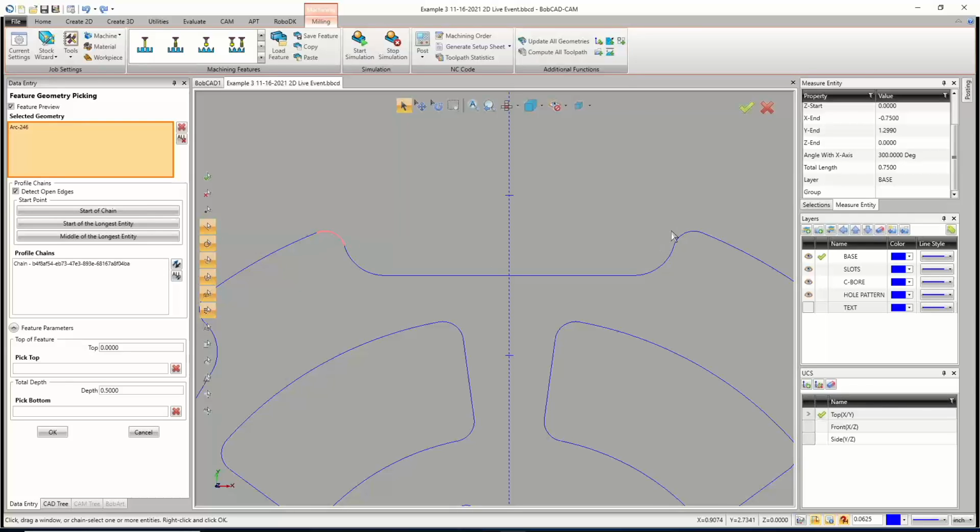You don't actually have to follow the chain. You could just jump over to it. But we want to go to the final radius, find the midpoint, and then go past it a little bit. You don't need to be right at the end. About 3/4 of the way down the line is perfect. Then we're going to hold shift and click. And that's going to chain all those geometries in between together. And that's why having that clean up optimize is super important.